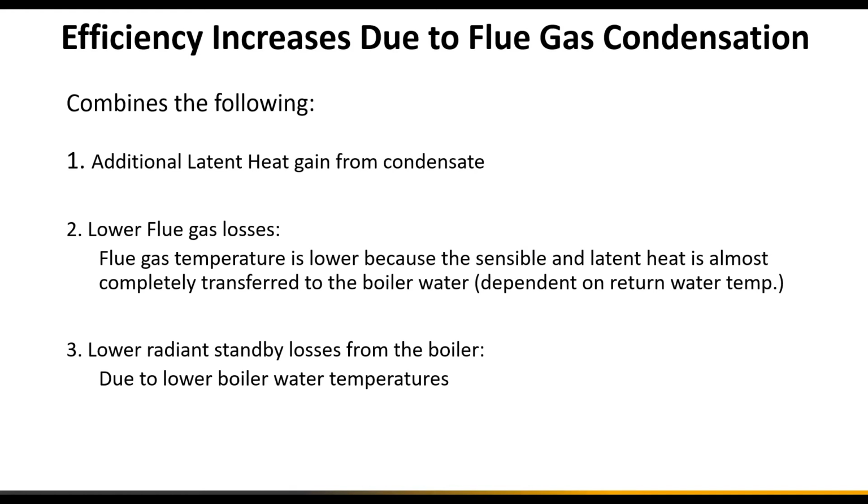First of all, of course, we regain a portion of that latent heat from the condensate. We're not having all that water vapor go up the chimney. We have lower flue gas temperature, so we'll also have an increase in the sensible heat gain. And also, the boiler will not be nearly as hot. And a good portion of our venting system is typically inside the building, and it will have a lot less heat going up that venting system. So we're really keeping the heat where we want it.